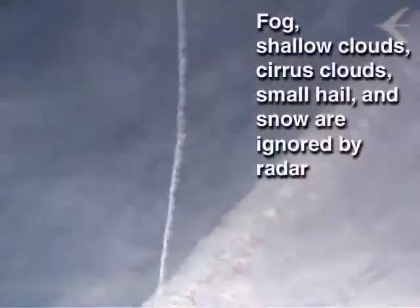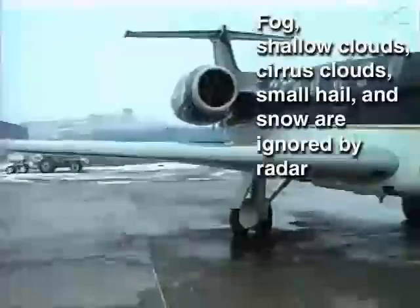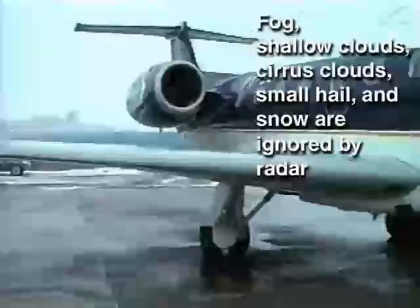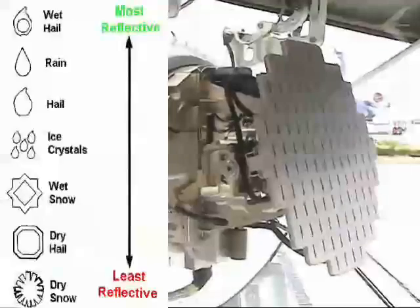The harder it is raining, the more energy will be returned. Fog or shallow cloud formation will be ignored by the radar. The energy is simply absorbed and no return is provided. Frozen water, cirrus clouds, small hail, snow, is crystalline. Thus, the pilot will see no return at all. Let us know what the radar can see.